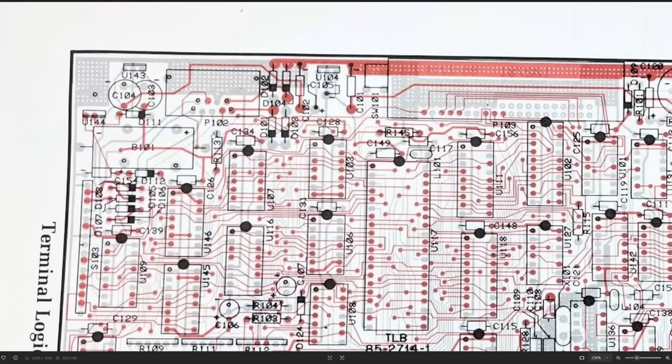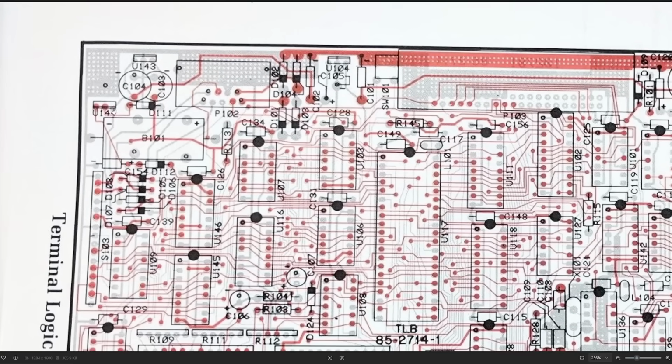And then the positive terminal goes up through this resistor. And it looks like the trace makes its way over to this diode, which then goes over to this transistor U144, where this pin of the transistor makes its way over on this red trace over there to C102. That's the tantalum that actually shorted in part 1. And we know that tantalum is the one that was around 12 volts because this is the output of the bridge rectifier, and then there's the capacitor that smooths it. So this voltage rail is pre-regulation, and this must have something to do with the battery charging circuit.